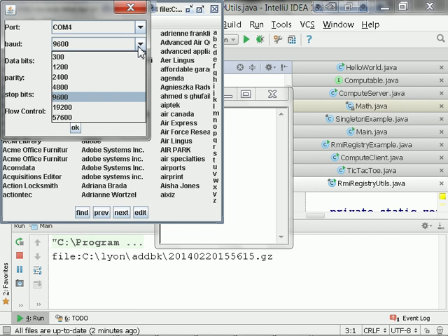So as a result, if you told me, well, gee, I have a 1024 symbol set, or symbol constellation, then I'd say, great, log to the base 2 of 1024 must be 10, because 2 to the 10 is 1024. How many symbols per second do you get? What's your baud rate?